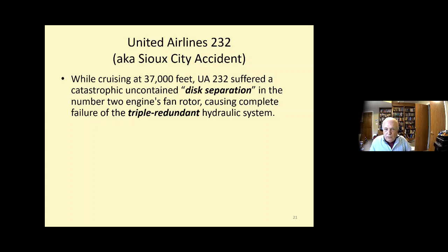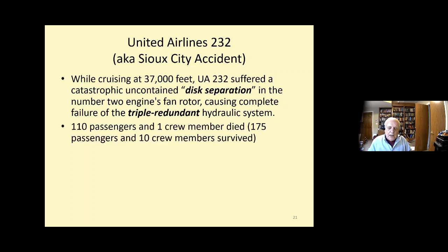all of those hoses were routed together. And when the disk separation occurred, which is basically an explosion of the engine, disk separation is kind of a euphemism, it severed all 3 of the hoses simultaneously. So these were not independent events, of course, and that's where the theory of redundancy sort of falls apart if you have that kind of dependency.